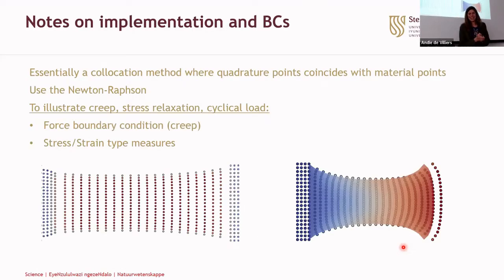Okay, so a bit of one slide on implementation only. So it's implemented for the test cases. We've only implemented in MATLAB, really using a collocation method where the quadrature points are at the same point as the material points. And it is a nonlinear equation, so we use the Newton-Raphson method to solve this equation.